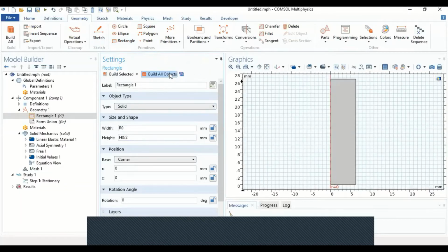After drawing it, you can see this rectangle, which is half of the bar, and if we rotate it around this red axis, it's going to create a cylinder, which is our end product. This would cut down on the mesh elements and the computation time to simplify the model further and make it run faster. Since you don't have to compute the whole three-dimensional model, you just compute a slice and rotate it around a 360 axis.